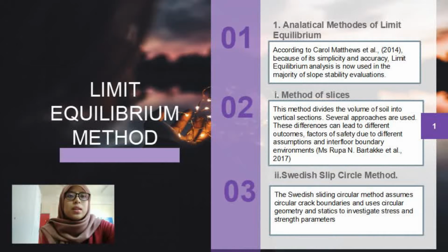Limit equilibrium method. According to Kara Matthew, 2014, because of its simplicity and accuracy, limit equilibrium analysis is now used in the majority of soil stability evaluations. This approach includes slicing the slope into small slices and using reliable equilibrium equations such as force or moment equilibrium.